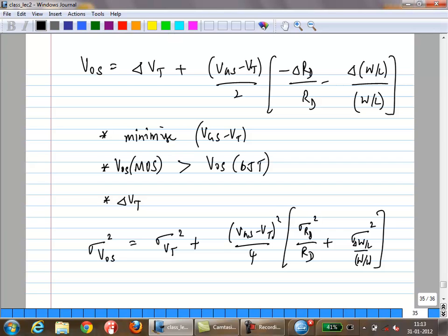So what I'll do is I won't do it for the full differential amplifier. It's a little bit involved, you can do it by yourself, it's not that difficult. I'll just show you how to do it for a resistor. For example, if you have mismatch between two resistors, how you would separate it into a differential and common mode half circuit. Then you can try it out by yourself and see what happens to the other parameters of your differential amplifier.